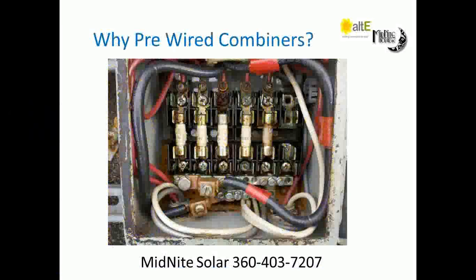But again, I want to stress that in an emergency situation, a Sandy type scenario, where the grid is down because of a storm, we really don't care about 3-stage charging on the batteries. We really don't care about being mean to the batteries. We're going to use them. We're going to use the daylights out of them, and when the grid comes back, they'll go back to float charge, and they'll sit there for another year or 2.